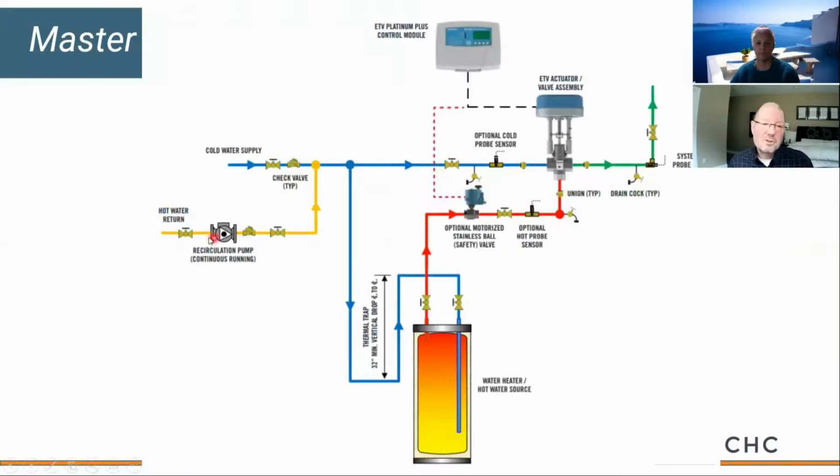So we always want our recirc to tie into our cold water line so that it can either pick up heat from our storage tank or a water heater, or continue on as cold water and serve either port of our tempering valve, with the goal of giving us flow out here to our system so that this valve can modulate to maintain tempered water.